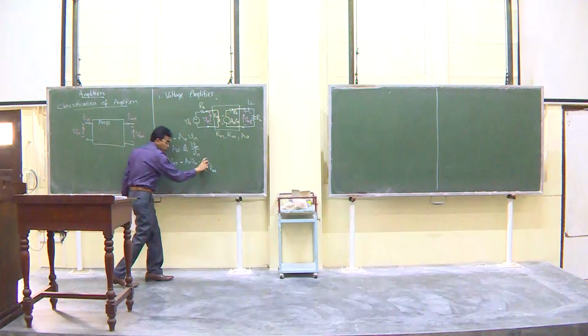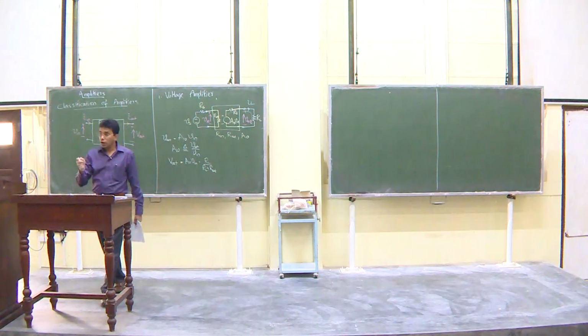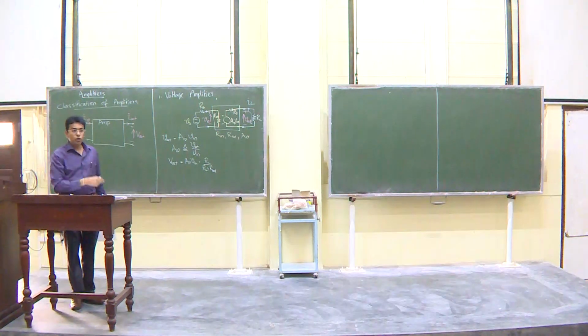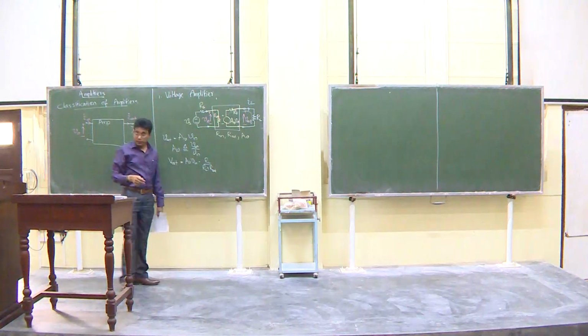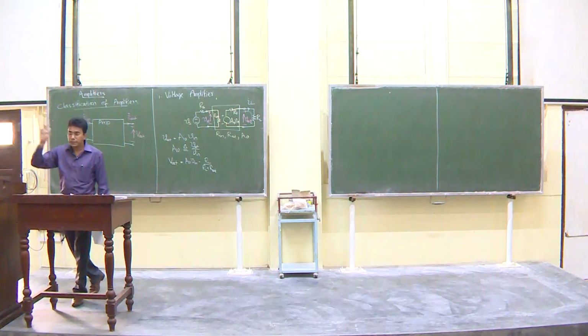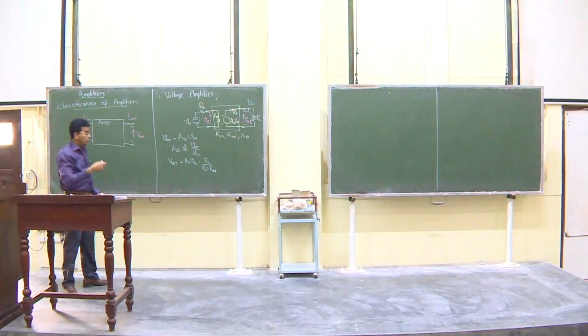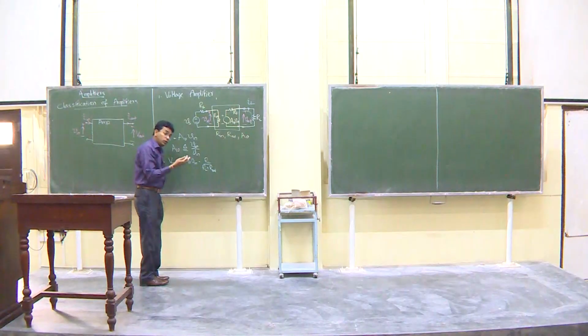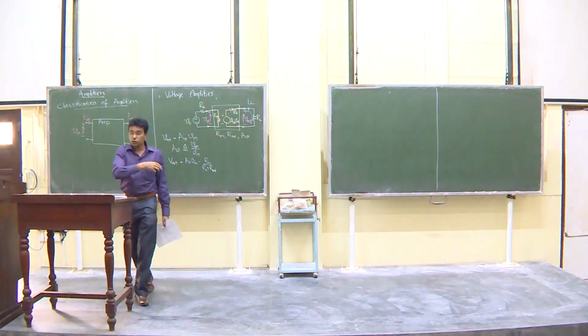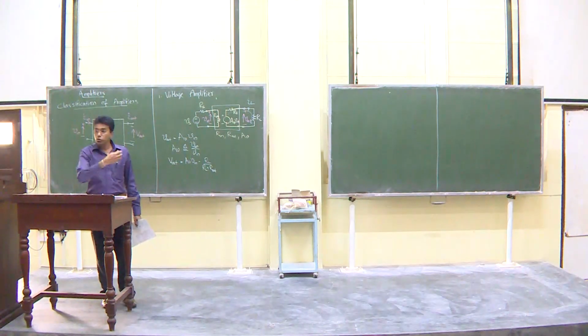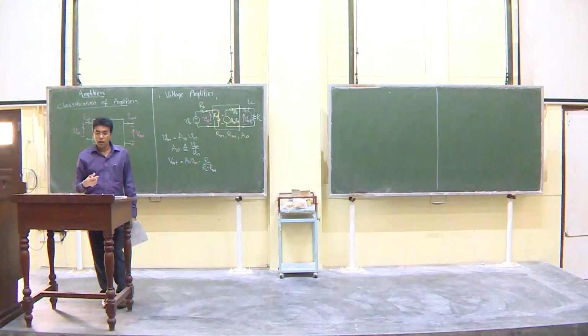So this quantity is always less than or equal to 1. It can never be greater than 1. If this R out is 0 in the ideal case, then the whole voltage appears at the output, otherwise there is some drop. So for a voltage amplifier, we prefer R out to be 0, so that as much as possible you get that amplification out.